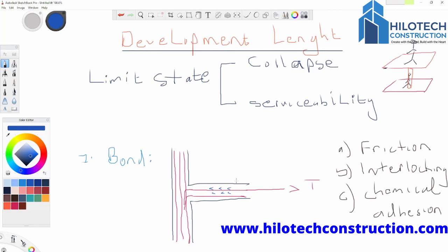Okay, so now let's look at one point here. We all know that this is a beam. Now let's say this beam is loaded like this, and this load can come from the slab, because as you know, each slab that you find, like the slab I was talking of up here, is being carried by the beam. Now it is this beam that transfers the load to the pillar. And you have to understand one thing: all these components of a structure, from the beam to the pillar right down to the footing, are not there to carry the load of the building. Nothing carries the load of the building. They're just there to transfer the loads.